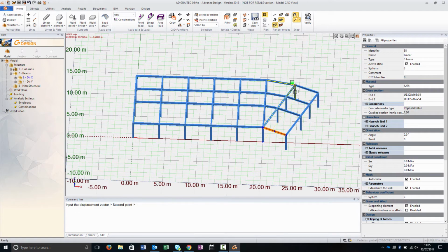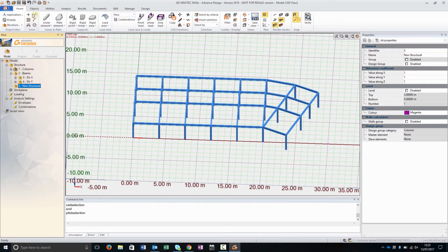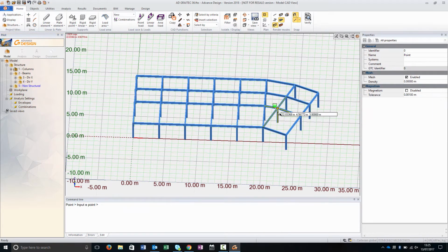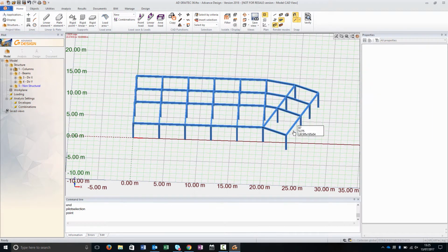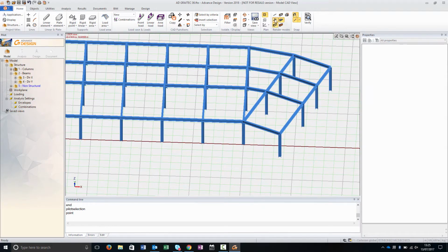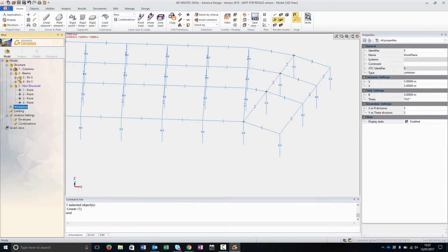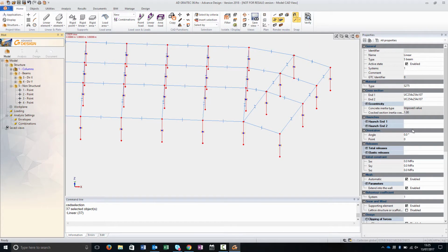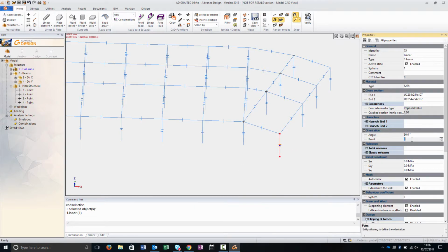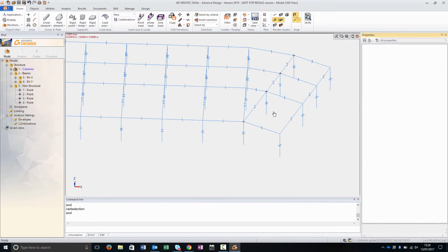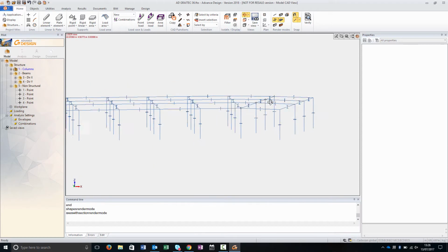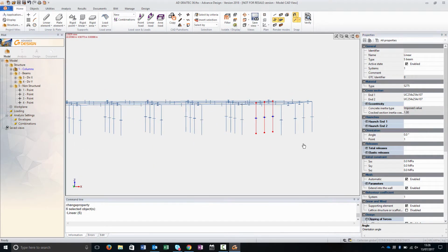To do that, we are going to place non-structural points that will help us to give the wished direction to all our pillars. First of all, we are going to change the angle by 90 degrees for all our columns. And then, thanks to the point we have inserted, we can give the direction wanted to all our columns, which will be looking at the point placed. Finally, we set the direction of these 3 columns towards point number 1.